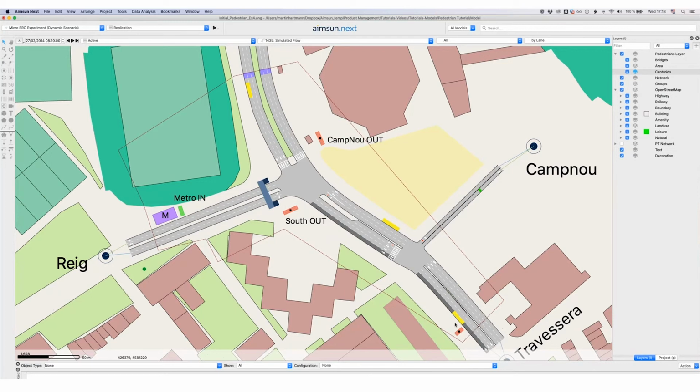So the cost is obviously composed of a few components, such as the travel time, of course one of the most important ones, either for walking or for this combined trip. For the one with PT, then it's of course the waiting time component, if there is any transfer component, if we model any fare, and so on and so on.